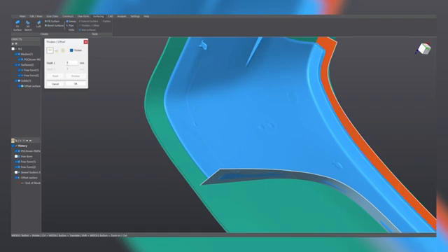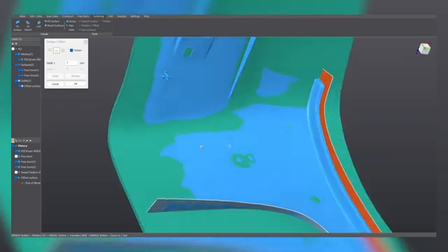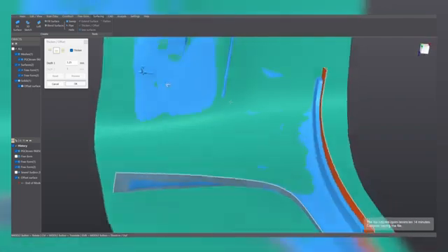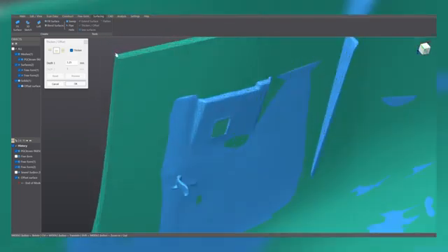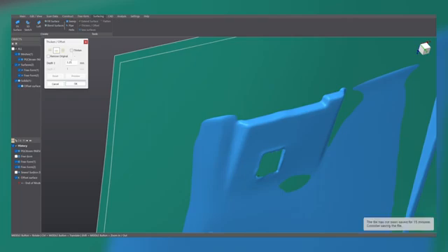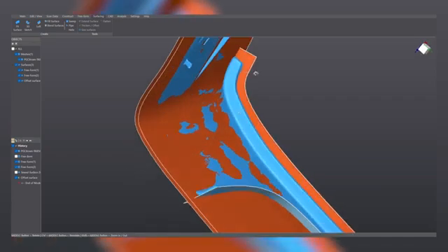Now, we are going to try different values of thickness. Actually, it's extruding to the other side, you will notice now. So we have to invert this extrusion. And 3 looks like a good result. Let's try with 3.5, which might be too much. Maybe something in between, 3.25, adjusts well. We are going to use this value. And this result is a solid. Because we are doing the surfacing, we want to work with surfaces, and I want to disable, therefore, this checkbox here. Click on OK. And we have our first thickness, right?